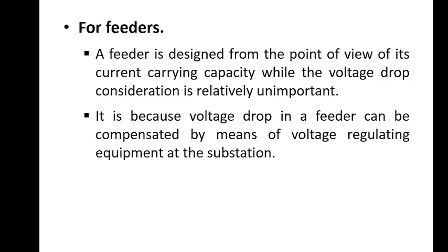The reason for this is that any voltage drop occurring in the feeder can be effectively compensated using voltage regulating equipment installed at a substation, such as tap changing transformers or voltage regulators and so on.